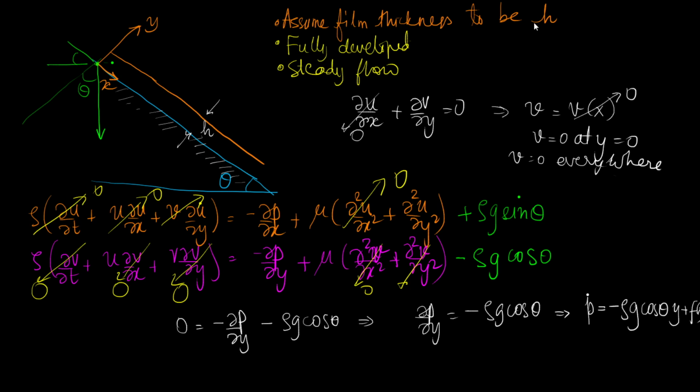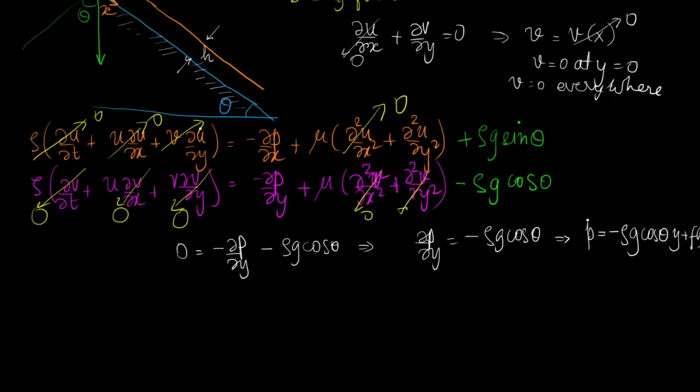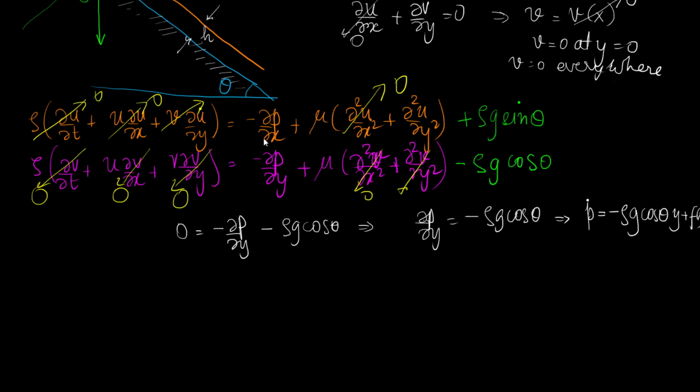And the important thing which is different from the other problems is p over here comprises the piezometric pressure rather than the static pressure. Okay, so the important thing is it must account for the piezometric pressure. So now when we take the derivative with respect to x, minus del p del x will be simply minus df dx. Okay, but anyway, let us proceed with whatever we were writing.